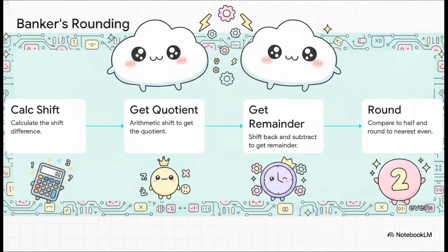And the best part is we can build this banker's rounding into a strict, step-by-step algorithm, effectively turning a complex mathematical compromise into a crystal-clear recipe for the hardware to follow. The circuit literally calculates the shift's difference, finds the quotient and remainder using arithmetic shifts, and then logically compares that remainder to the halfway point. It's just a beautiful example of translating a high-level statistical trick into the most basic hardware operations imaginable.